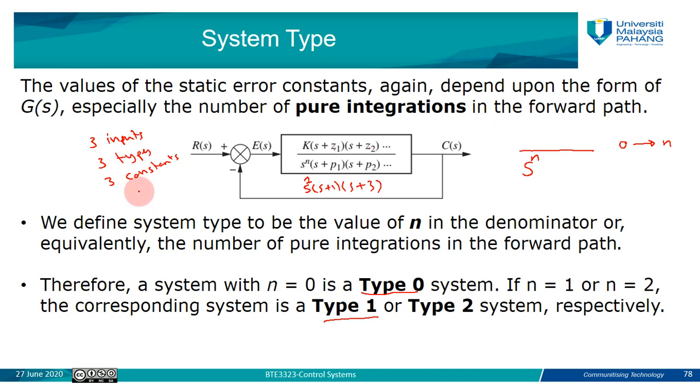We already mentioned position, velocity and acceleration when we talked about the type of the input and which input is preferred for each application. If you can differentiate between these three, you can know how to calculate the value of the steady state error for each case.